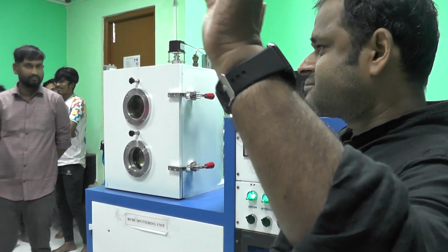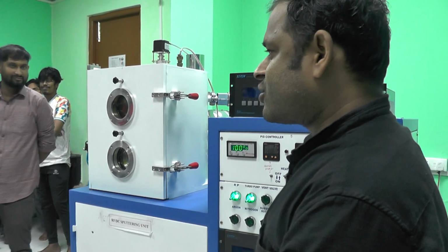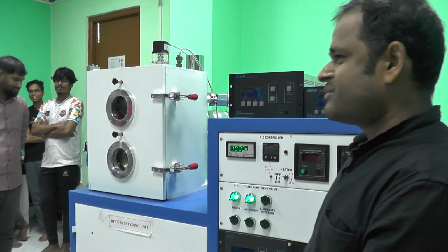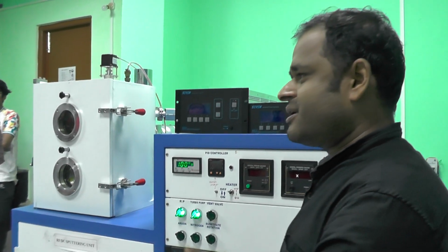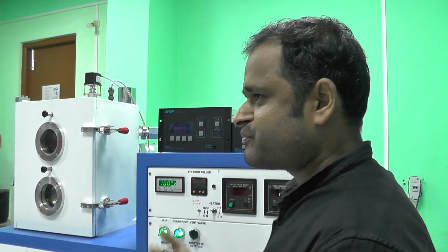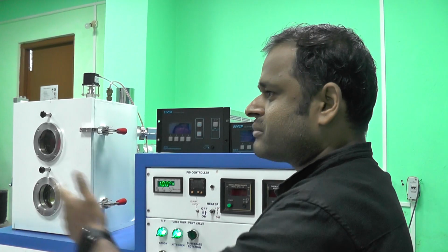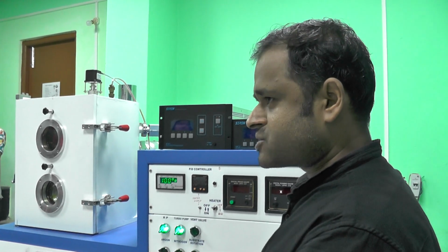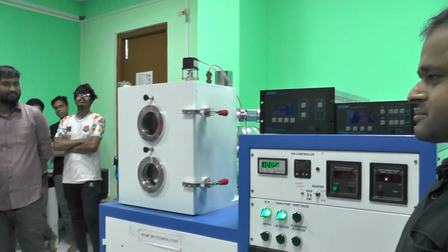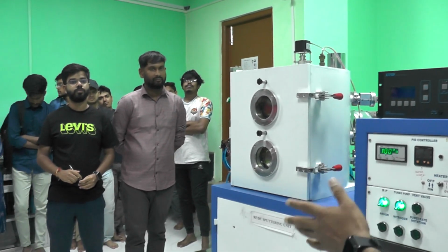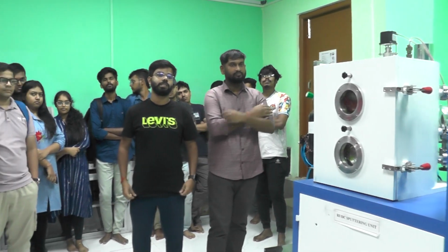Okay, good afternoon. Welcome to the Nanoelectronics and Emerging Memory Lab. I hope you have sound knowledge about sputtering and about 4-probe measurement. Before deposition, we have to prepare our samples, so we have to clean them. Many people use RCA cleaning and Piranha cleaning. So all chemical cleanings are there.